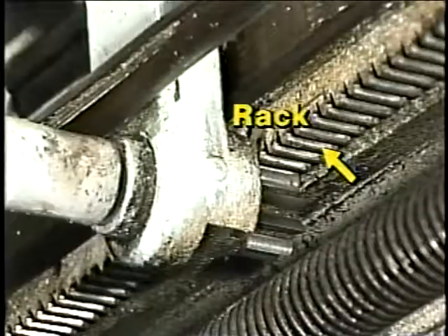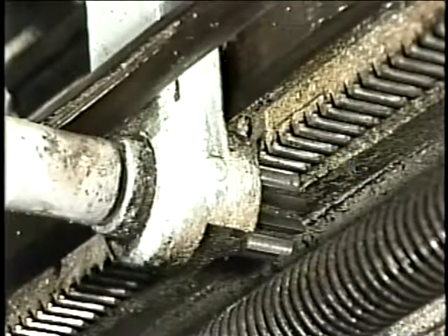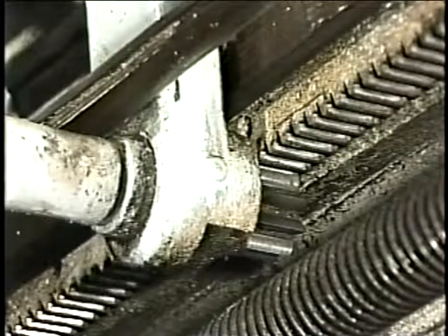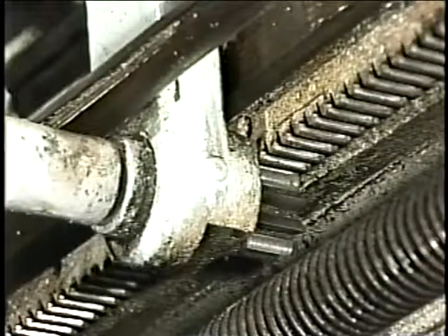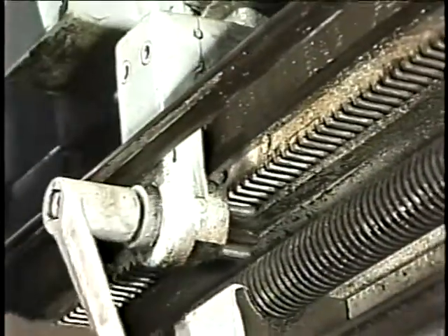As we do that, you should keep in mind that for almost every application of gears, the gear arrangement that's used will be different. Okay, now with that in mind, let's start by looking at one type of gear set called the rack and pinion. This is the rack, and this is the pinion. Depending on its application, the rack and pinion may be used to convert the linear motion of the rack into the rotary motion of the pinion, or, as in this case, rotary motion of the pinion into linear motion.